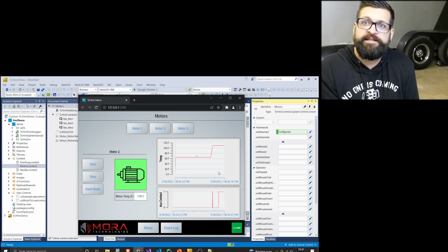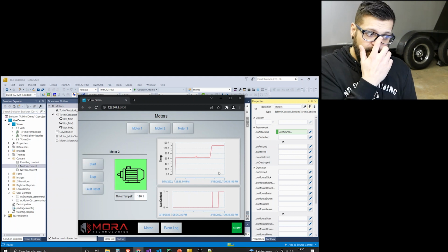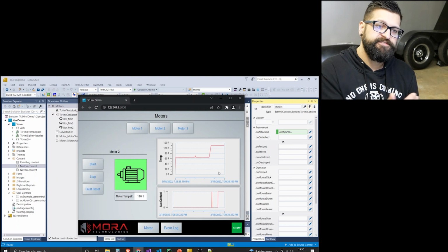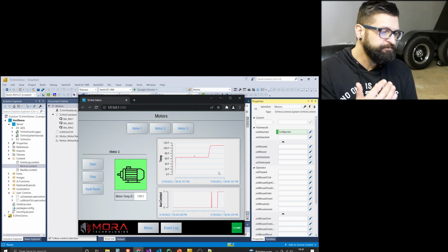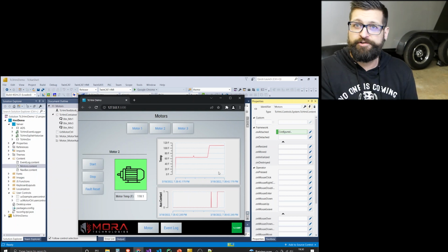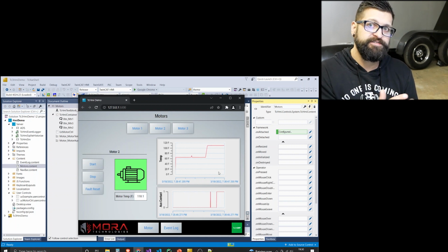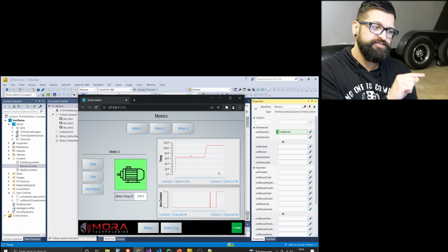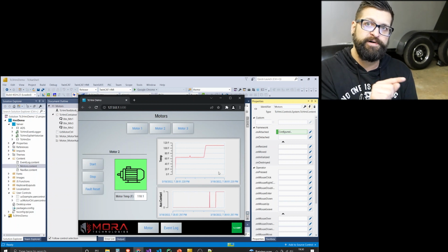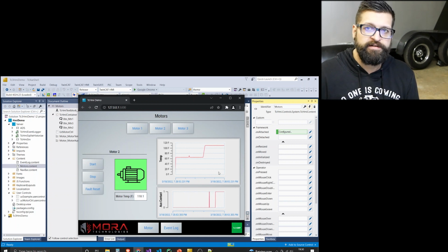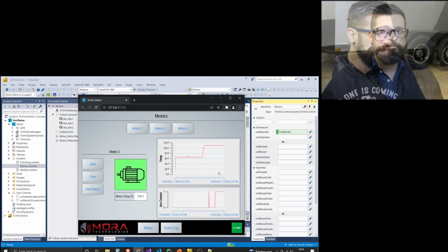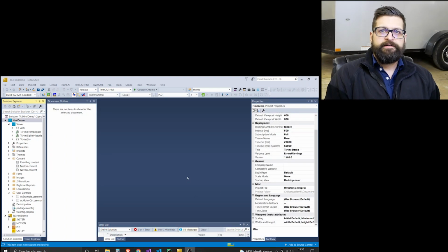That's something we need to be mindful of: if we're recording a historized value at a 1 second interval and we zoom in to 200 milliseconds, there's 1 second of dead time between samples, and we can't trust that value. It's just a graphical interpolation between those 2 points that would give you a nice slope. Anyways, it's just something to point out. Sorry about that, my camera died.